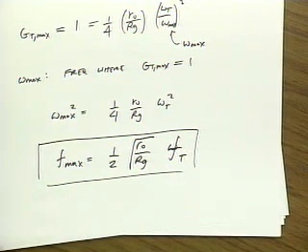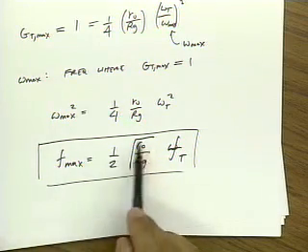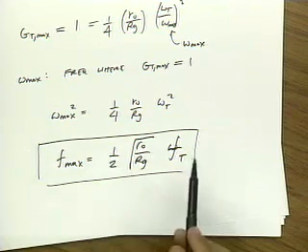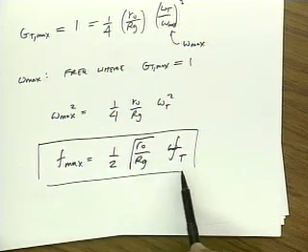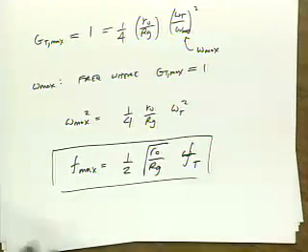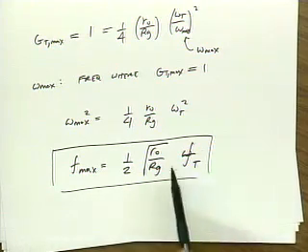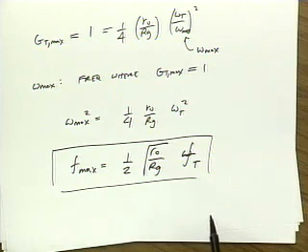So under the simple approximation that we made, a unilateral device, we can see that as long as I can maximize the ratio of the output impedance of the device to the gate resistance, I can go up to really high frequencies. In particular, you can even go higher than Ft. Whereas Ft characterizes the bandwidth of a wideband system, in an RF narrowband system Ft is not that relevant because I can always tune out my parasitics. But I can't do that at an arbitrary frequency.